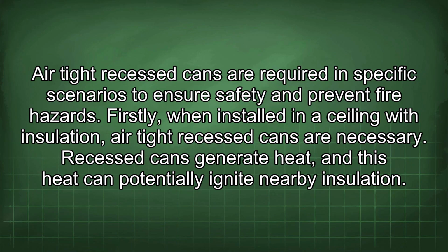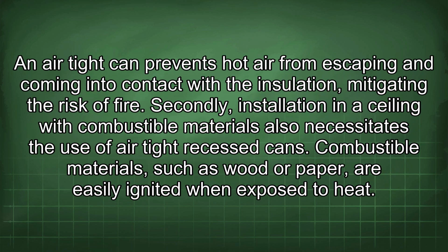Airtight recessed cans are required in specific scenarios to ensure safety and prevent fire hazards. Firstly, when installed in a ceiling with insulation, airtight recessed cans are necessary. Recessed cans generate heat, and this heat can potentially ignite nearby insulation. An airtight can prevent hot air from escaping and coming into contact with the insulation, mitigating the risk of fire.